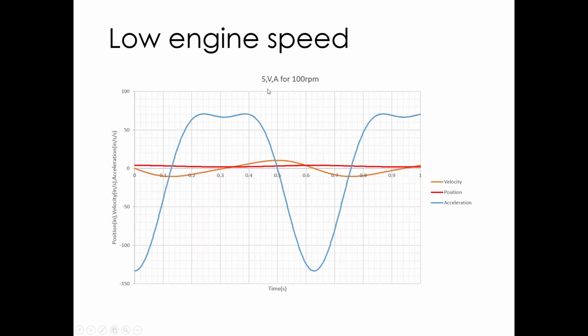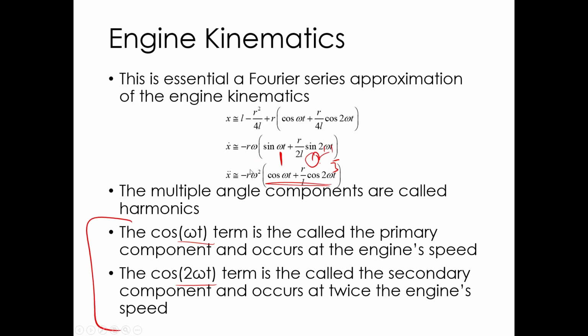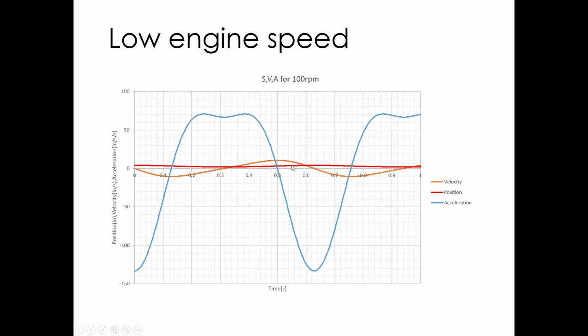Okay, so that's just the acceleration of the piston. Actually, yeah, that's just the piston. That's not the connecting rod, right? Because this is just x. So this is just the acceleration of the piston. So again, this component comes from the geometry of the connecting rod, but it doesn't include the vibrations from the connecting rod itself. And it doesn't include the gas force and gas torque either.